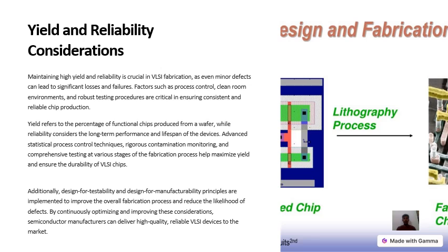Factors such as process control, clean room environments, and robust testing procedures are critical in ensuring consistent and reliable chip production. Yield refers to the percentage of functional chips produced from a wafer, while reliability considers the long-term performance and lifespan of the devices. Advanced statistical process control techniques, rigorous contamination monitoring, and comprehensive testing at various stages of the fabrication process help maximize yield and ensure the durability of VLSI chips.